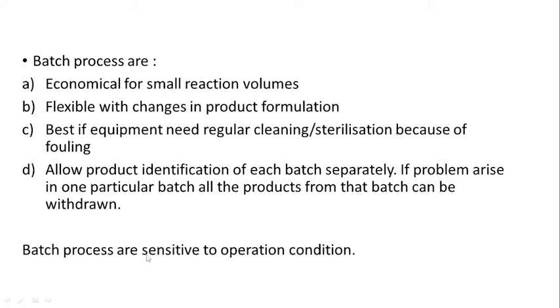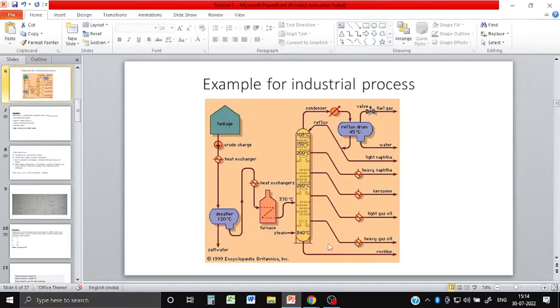But batch processes are relatively sensitive to operational conditions. If the operational condition changes by a little bit, like if temperature exceeds by 10 degrees Celsius, the yield of the product might not be as per our requirement.